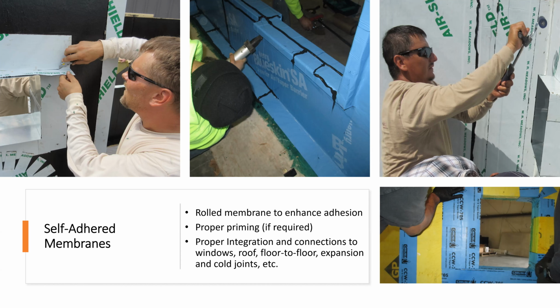And one of the reasons why is when you just kind of hand press these things in, you're not getting into those gaps and cracks and crevices. So if you remember what I said about concrete masonry units, if you look at it microscopically, it looks like a mountain range. So if you're just kind of patting it with your hands, it means you're just having it stick to kind of like the top of the mountains and not the bottom of the mountains. So it means that your air barrier really isn't installed well to actually adhere. And it may not show up right away. So you can go, I do a good job, I come back 2 days later and it looks horrible. It could be a function that it simply wasn't rolled.